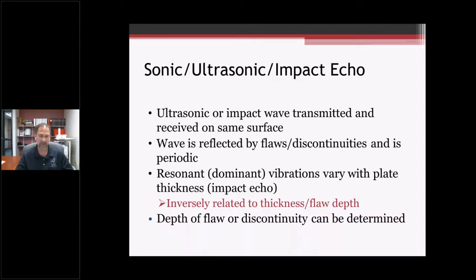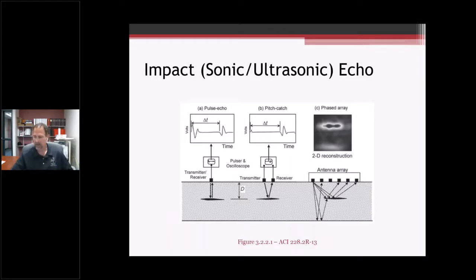That dominant frequency, some people call it a thickness frequency. It's inversely related to the depth. So as the frequency increases, the depth to your flaw, your discontinuity, actually decreases. And again, we can figure out what the depth is.